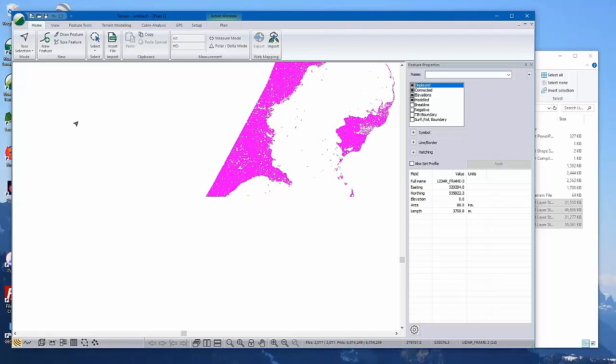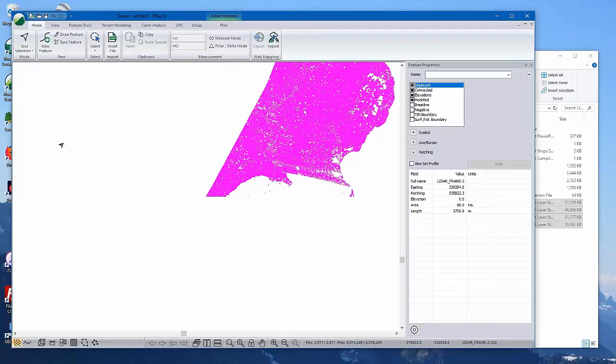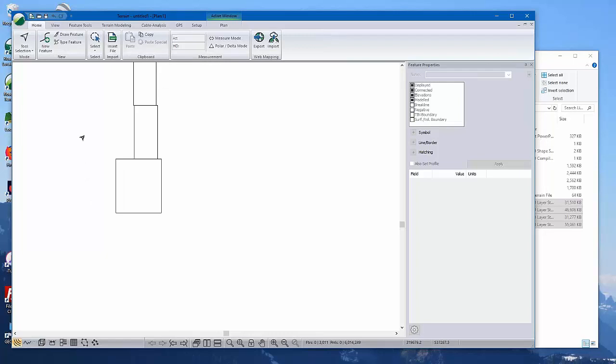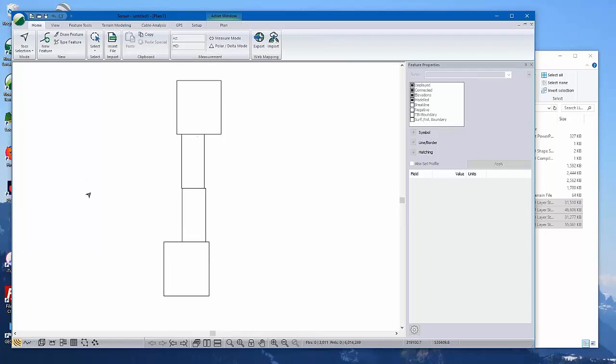And when you insert a file, the data comes in selected. And the first thing I want to do is to unselect it. And there's a little bit of a trick to that. First of all, if I have my mouse in the plan window and I hit escape, it'll stop drawing. If you ever get into a long, slow, painful draw, just move your cursor in the plan window, hit escape. And now that it's stopped drawing, I just simply select something in the white area of the screen, and now I have disabled the drawing of all those points.